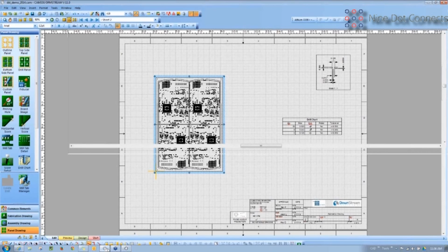So when we start talking about the DFM tool, it should be flexible, it should be powerful, and it should have tools to help you validate the issues once you run an analysis. Okay? Let's just think about it for a second. If you've got a typical board that has 5,000 or 10,000 holes on it, just one failure is 5,000 or 10,000 failures. For a lot of people, that's what makes them throw their hands up in the air and say, oh, I can't run analysis. I've got 10, 15, 20,000 errors. So the tool should be able to look at those errors in groups.